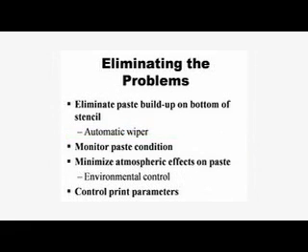Eliminating the problems can be difficult depending on the process. Here are some tips. Eliminate paste buildup on the bottom of the stencil, either by hand or with an automatic wiper. Monitor your paste condition. Minimize the atmospheric effects on your paste with environmental control systems. And control your print parameters.